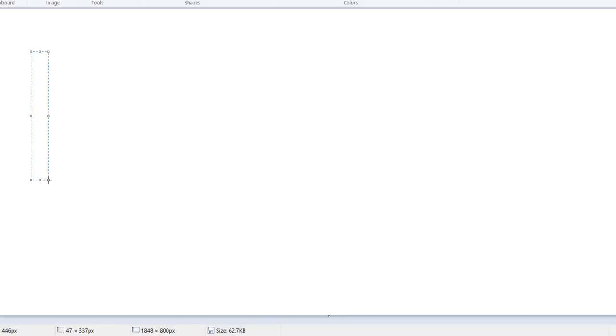Okay, now let's take another example. This time we are applying the load P exactly along the center line. Okay, but there is no horizontal load acting at the tip, so the moment at the base should be 0, because there is no lever arm and there is no horizontal displacement, there is no horizontal load.